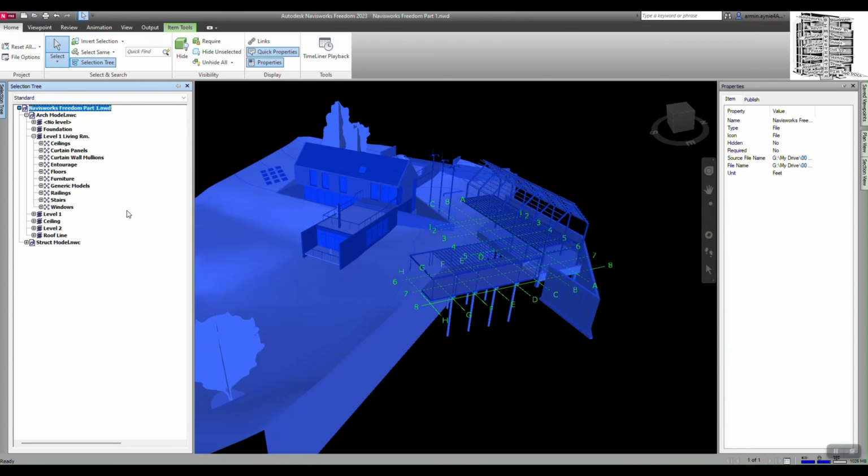First, we're going to hit the Review tab. The first item that we see is the measurement tool. When you click under Measurement, you can see different options: point to point, point to multiple points, area, angles. It gives you a variety of options to choose from. As soon as I click on Measurement, the lock gets turned on, and this tells me what axis you want to lock your measurement to. For the purpose of this one, I'm going to use just Z, so I can show you what I mean by that.